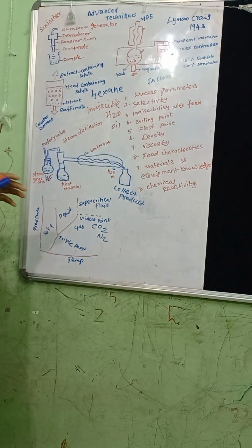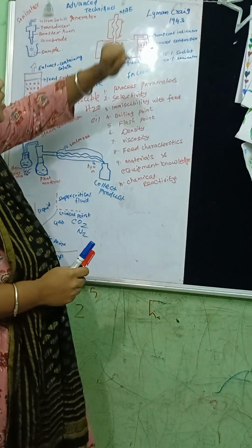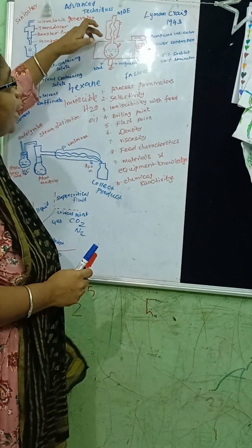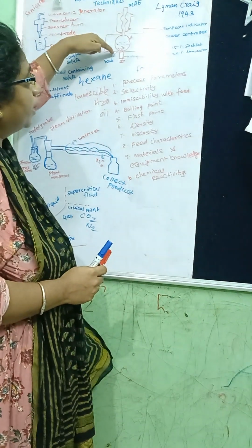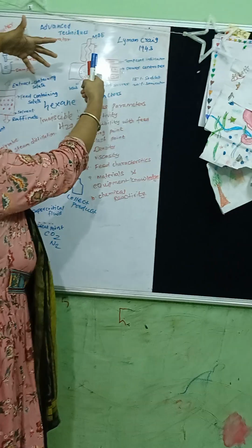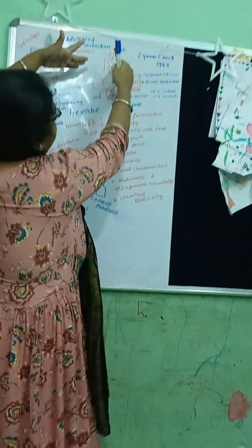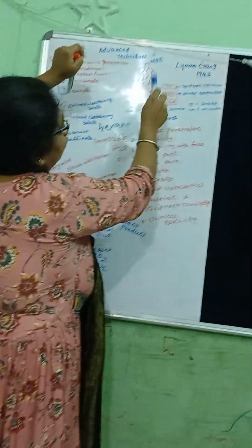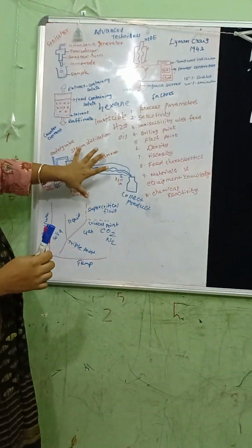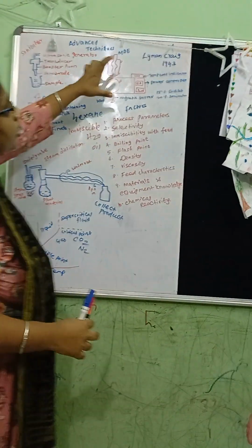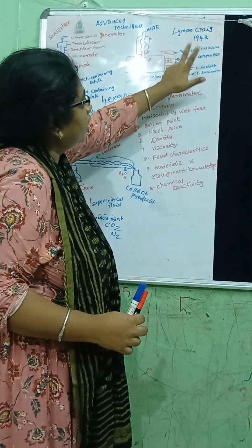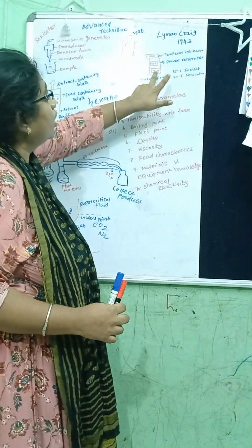The next one is called the microwave assisted extraction process. Here, the same round bottom flask which is having the liquid. This is the magnetic bead which gives the magnetic stirrer. It will revolve the liquid sample. This is the condenser, this is the water inlet and water outlet. Everything we do in the steam generator process is automatic, no? Here we are controlling it using the microwave, which controls the temperature indicator and also the power controller and also the time.